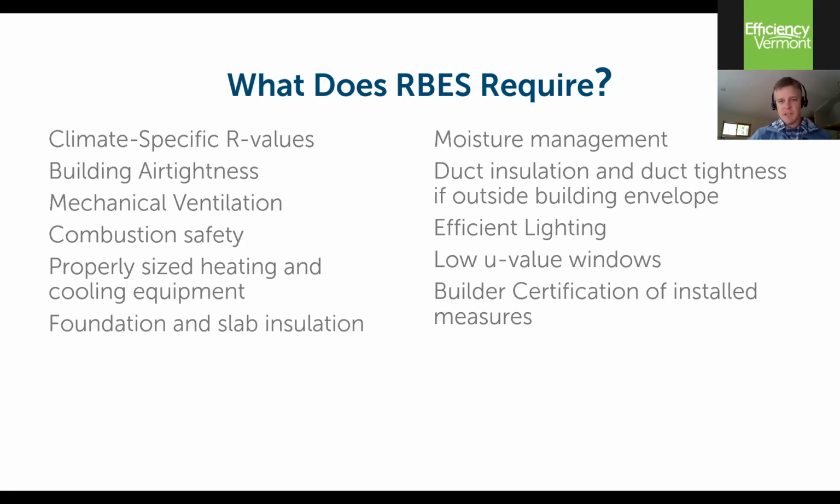Insulating slabs and foundations. Concrete is an excellent conductor of heat, and not insulating it is a major ongoing source of heat loss and comfort issues. Moisture management aligns directly with mechanical ventilation requirements, and moisture unchecked in a building has huge impacts, not only on potential for mold and mildew growth within the building, but on indoor air quality, on occupant health, on building durability. So a big part of the puzzle here.